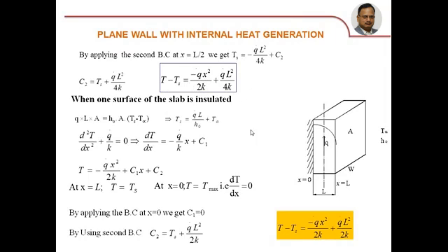So the temperature distribution equation can be found by using the fundamental governing equation for conduction with internal heat generation under steady state and one-dimensional conditions, solving that, and thereby applying the boundary conditions. So first take the equation and integrate it to get the temperature distribution, and then identify the boundary conditions, and substitute them to solve for C1 and C2. And to get those boundary conditions, you may have to use the total amount of heat generated as a source to determine the surface temperatures, etc.